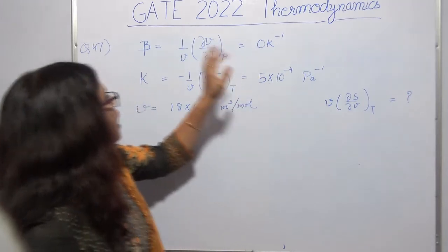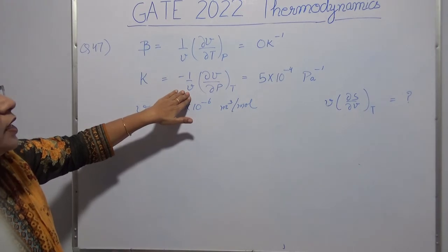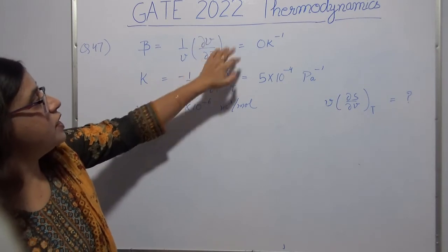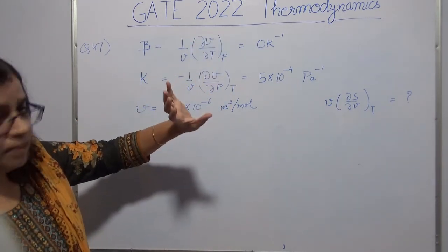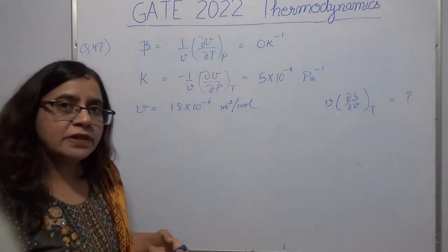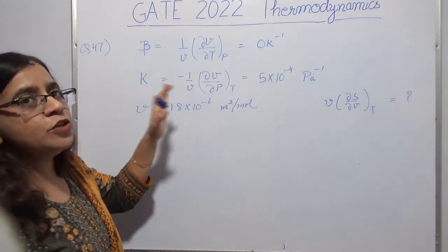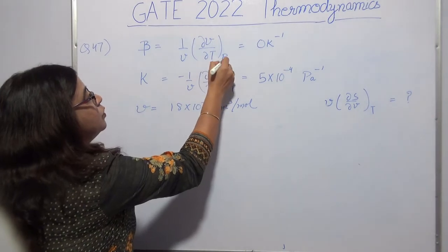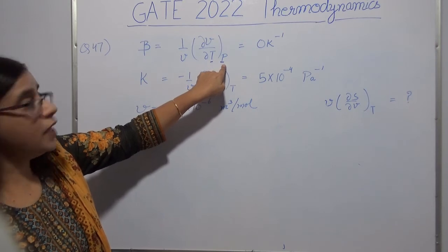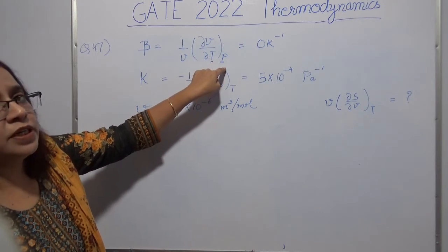Usually what I do is, if I have some known quantities, like say I have these two known quantities, I will first try to write a Maxwell relation which contains either this term or this term. First of all, which equation to write, from which you will derive your Maxwell relation, I usually figure out by seeing these two. Okay, so this is T and P, so this gives me a hint that I should write the equation which is in the variables T and P.